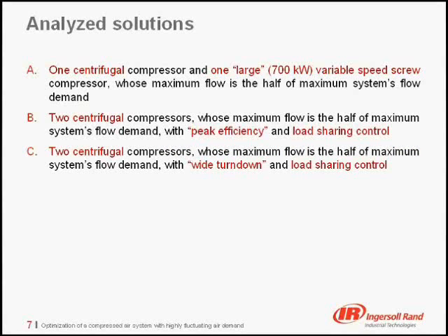The third solution considers, in this case, two centrifugal compressors designed with wide regulation range. Also in this case, like for all the next solutions with multiple centrifugal compressors, the load sharing control is always foreseen, since this control system always allows reducing the blow-off of the centrifugal compressors by extending the system's regulation range.